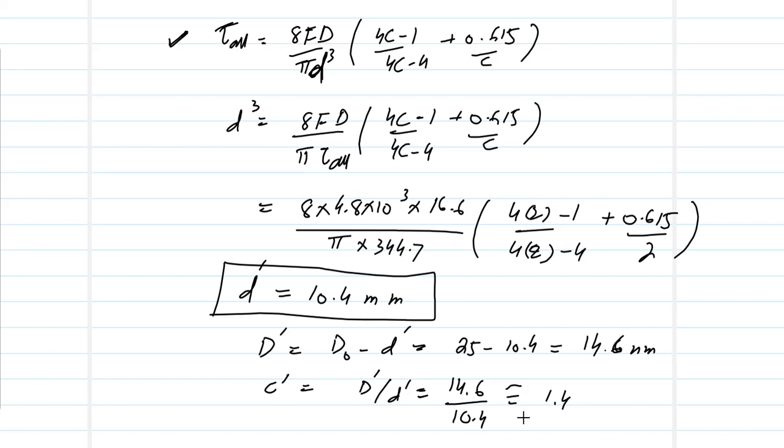Okay. If it is clear to you till now, we have designed three things, and I'm again repeating. At first we don't know capital D, small d, and C. So what we have to do first is consider the wire and just provide torsion in it, because even the wire in a spring experiences torsion. From this I found the small d and the capital D. Now I have to check whether the values are compatible when this wire is converted into a spring. Then I used a stress formula to again find the wire diameter, and what I found is that the wire diameter is slightly larger than my previous assumption. Now I have to use a larger wire diameter. And with our larger wire diameter, I have again calculated the mean diameter and spring index.